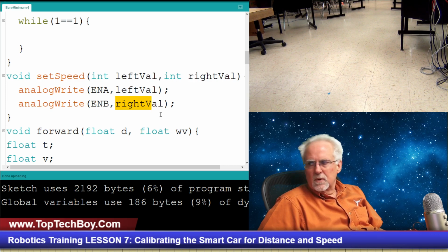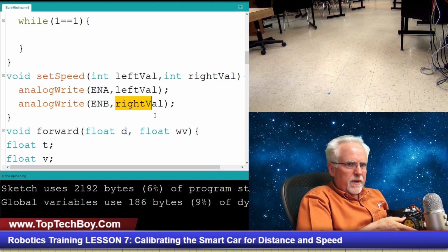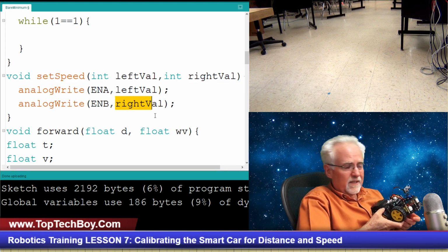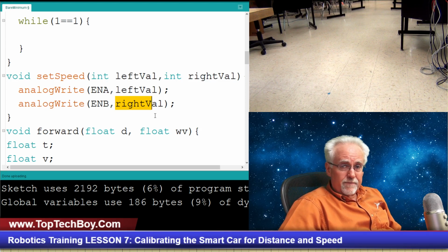So that looks right, but it's just as I'm going a long distance, it's kind of like the wheels on the right are running a little bit faster than the wheels on the left. And again, this is just showing you one of the limitations of trying to do dead reckoning. When you're doing dead reckoning, it's just not going to work absolutely perfectly.